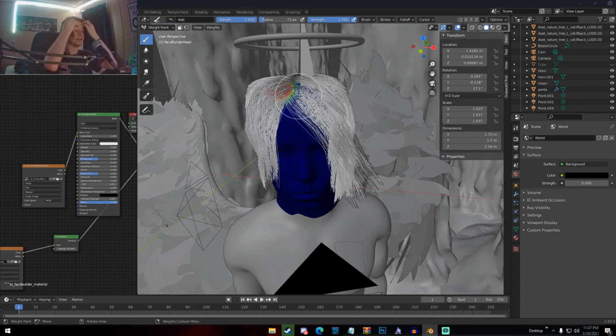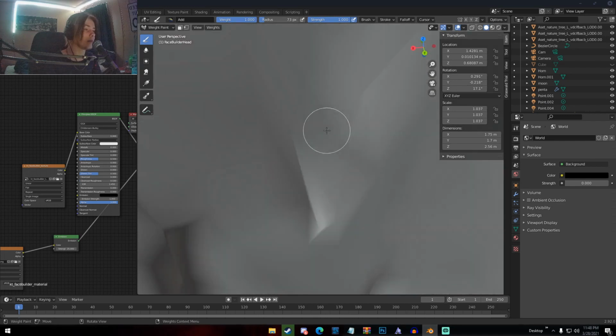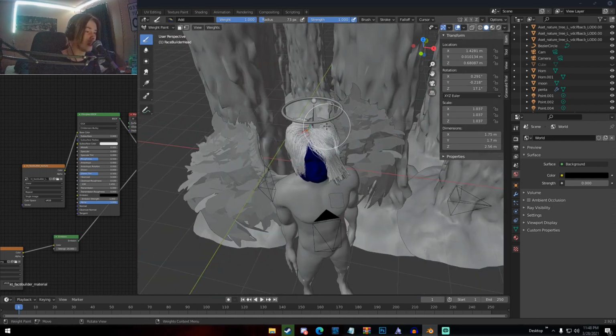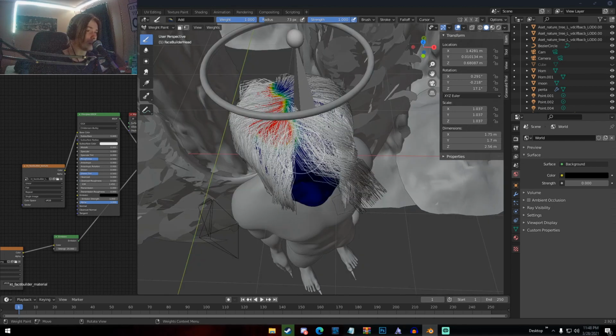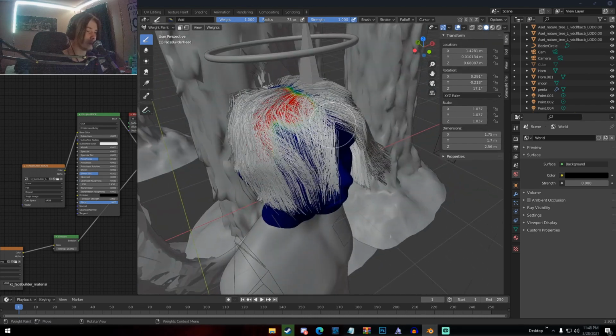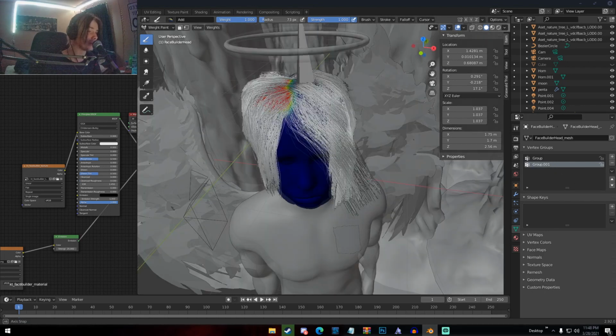It makes it a lot easier and stuff like that. So once you have marked where all your hair wants to be, if you have multicolored hair or hair that is split dyed like I do, then you're going to want to make two particle systems of hair. So just do one side and then go down here to this vertex group, little icon, this little triangle, click this plus and add a new group, and then just do the same thing on the other side.